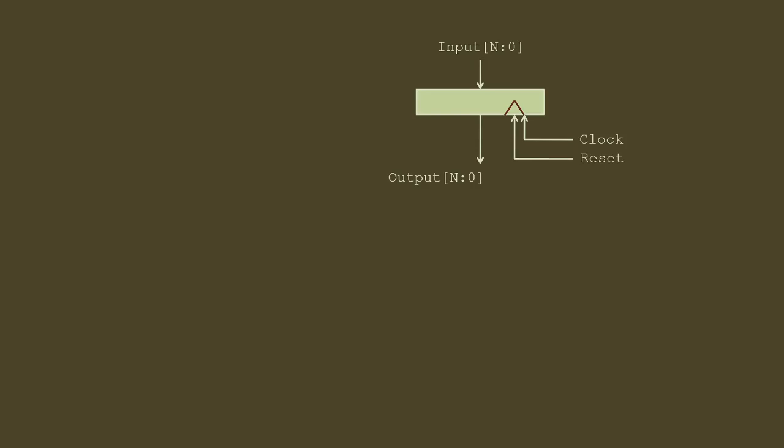By rising edge, we mean that when the transition is from 0 to 1, or by falling edge, what we mean is that the transition is from 1 to 0. Most of the circuits work on rising edge of the clock, but at times we use falling edge of the clock as well. So let me explain with a diagram. Normally, there is also a reset signal which sets its initial value to a known state. Normally, it's 0.